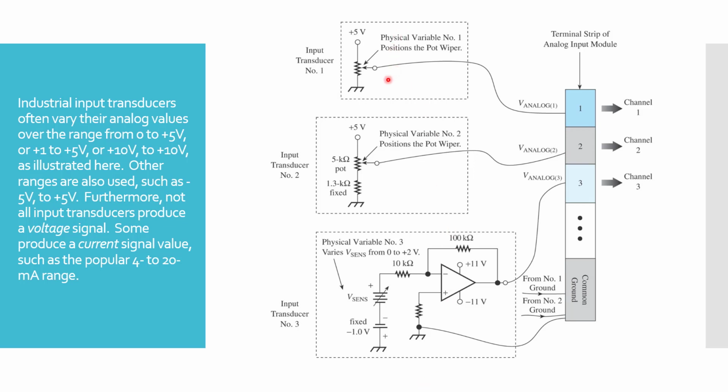So in this particular example, this is a variable resistor, and this is being moved probably by something that's moving. It's attached to something that's moving. So as that item moves, I get a different voltage, and the voltage that I receive at my analog input that's going into my processor is telling me where this item is, because as the item changes position, the voltage changes. And so the analog signal going into the computer is following that change.